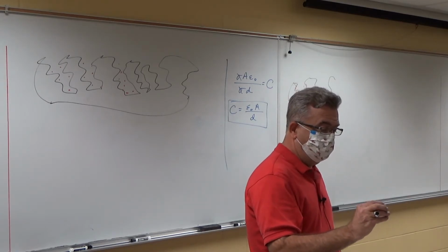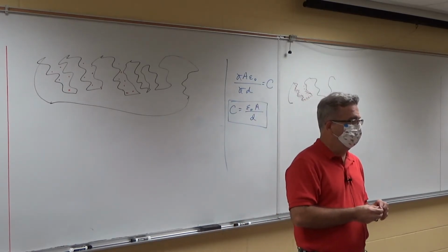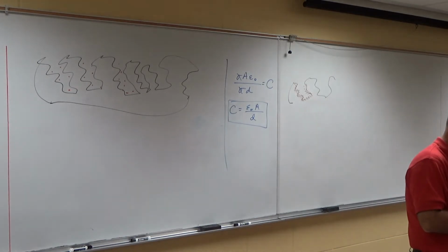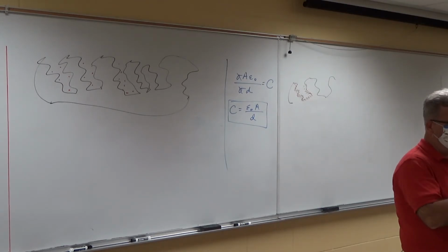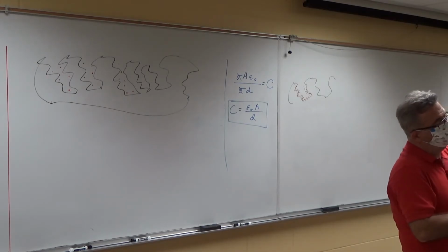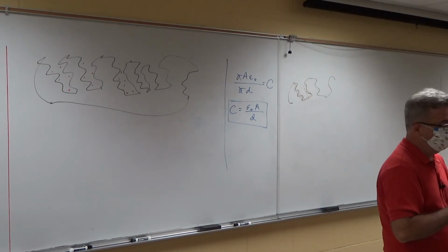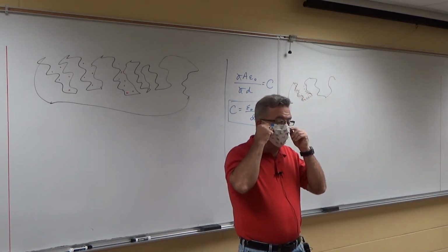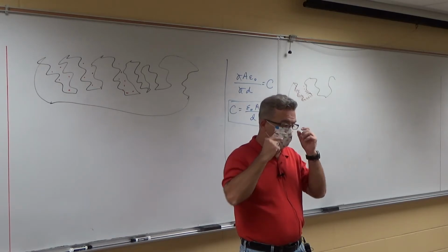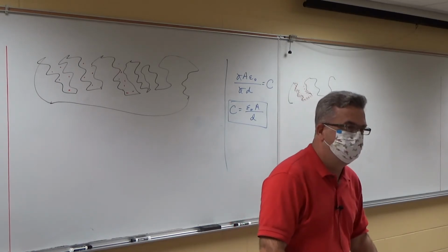This is rated at 5.5 volts, so any voltage between 0 and 5.5 is fine. Plus it's a so-called electrolytic cap, so it depends on the polarity as well. This is the negative side, that's the positive. You can't really see the leads very well, but there are two little leads down here. When you hook the negative to this side and the positive to that side, it's fine. If you hook it in reverse, pow. So that's the kind of caps we're going to use in lab. We're going to have electrolytic caps, and if you hook them up with reverse polarity, it's bad.